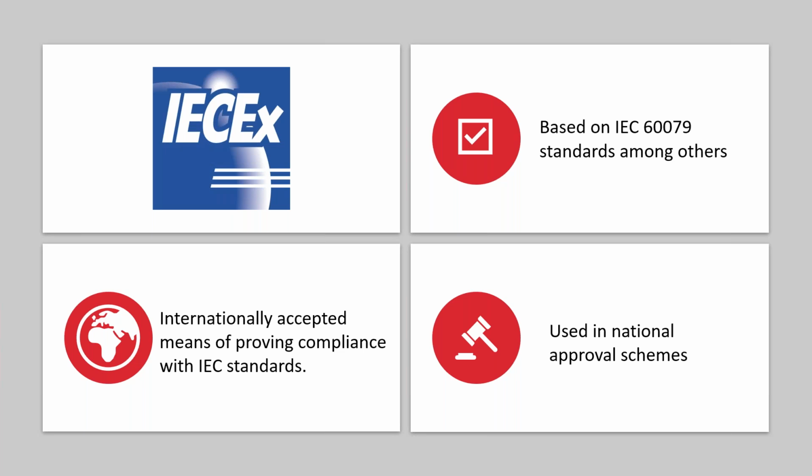So look out for IECEx certification data, which manufacturers will generally publish on their website. So given that the IEC standards are used in many national approval schemes, IECEx certification can often be used to support any specific national compliance in which it's required, often negating the need for additional testing in most cases.